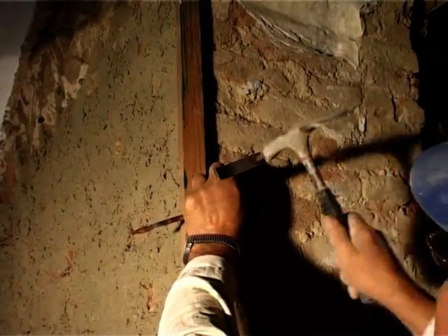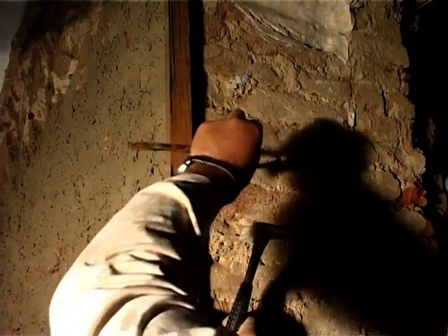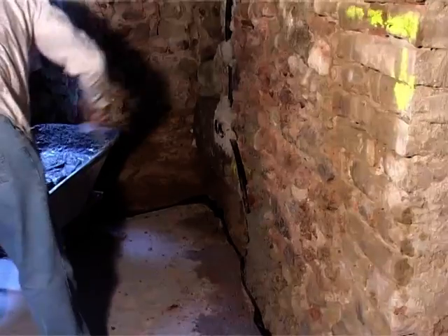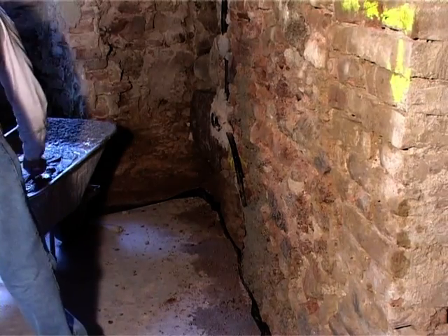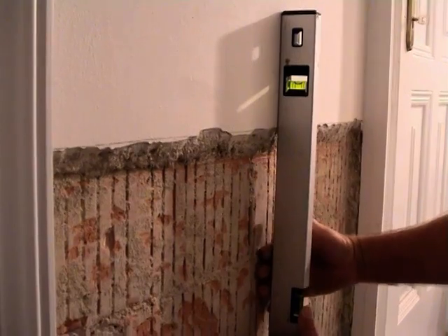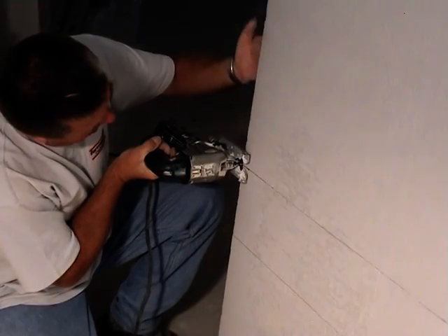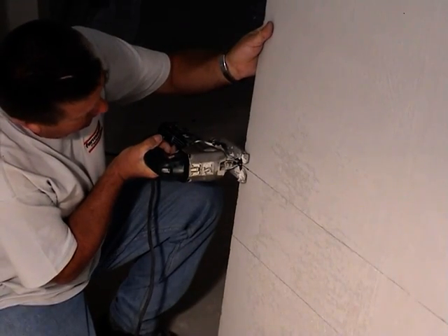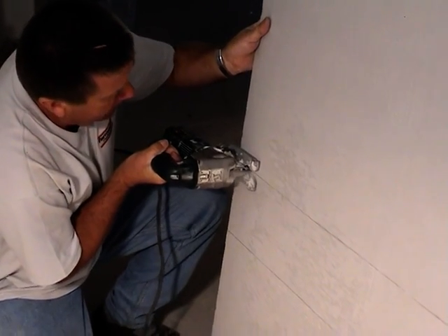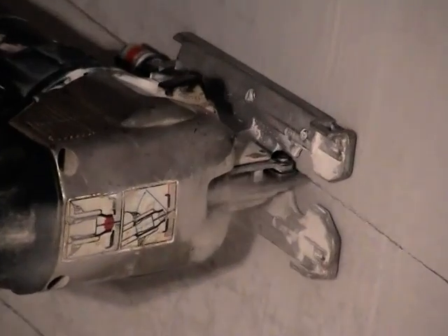If the wall merely needs a new coat of paint, it should be painted after the evaporation phase. According to the ÖNorm, Austrian standard, and according to our long years of practical experience, the actual plaster renovation should be performed only after the wall has been dried. One thus avoids migration of the salts into the new plaster and consequent undesirable chemical reactions.